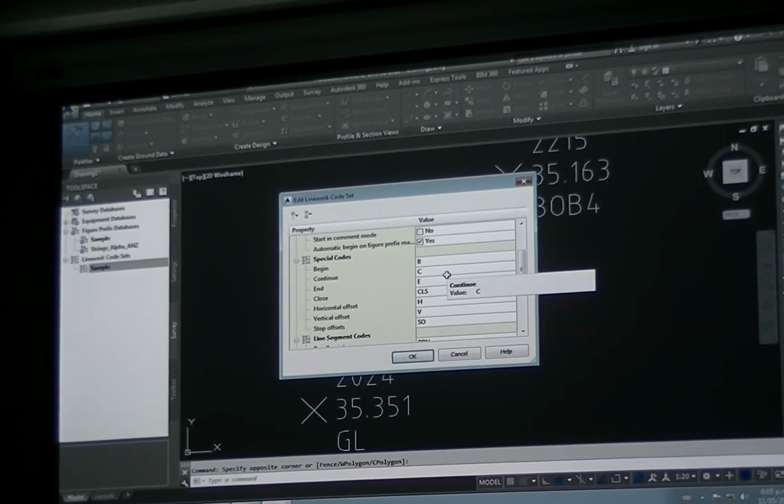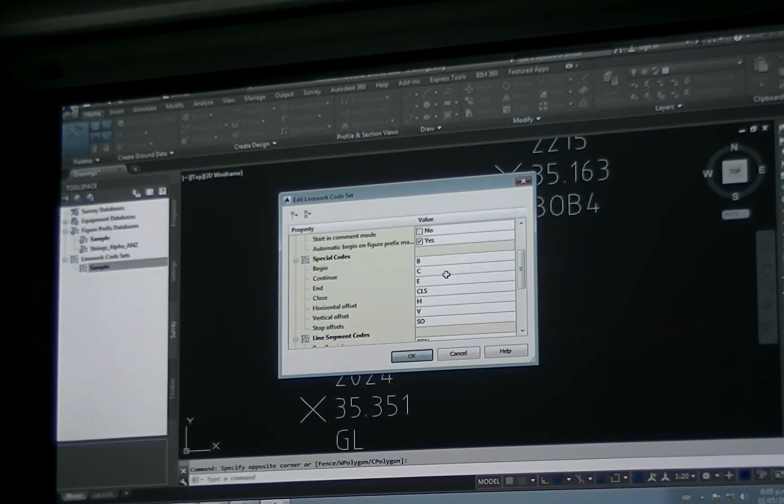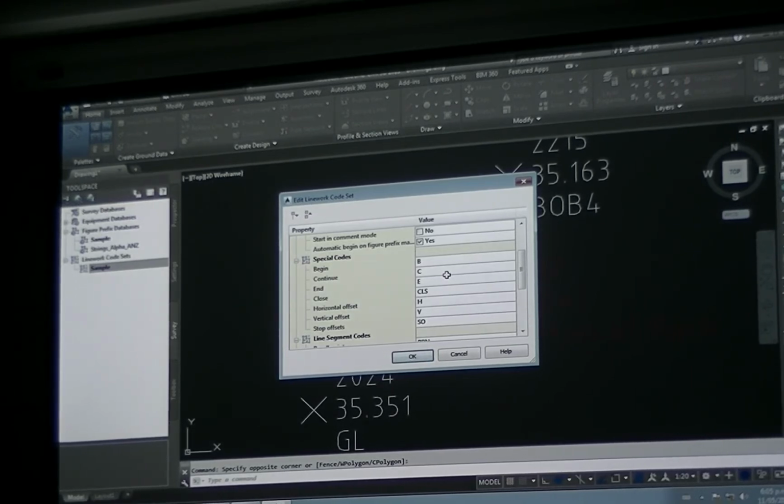But you can set up Civil3d to what they call field to finish. If you get all your settings correctly, your input masks correct, your description keys correct, it can do a lot of that pre-work for you. So you don't have to go into your drawing and put the centre line of the road through when you've been surveying. The survey's gone down the centre line of the road, think every 100 metres or 20 metres or whatever. You started the line in the machine, finished the line when you finished, and when you input the data, the centre line of the road's already drawn in for you.